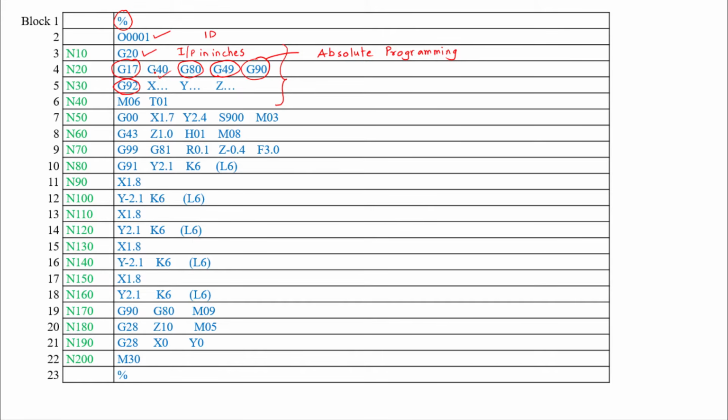So when the part is fixed on the machine table, we need to communicate to the machine tool its location in the work volume. So for that purpose, G92 with XYZ offset values are to be communicated to the machine tool. We will be seeing this in the coming slides. M06 is the tool change, which tells which tool has to be utilized by changing the existing tool in the spindle. So M06 T01 means the existing tool in the spindle will be replaced with T01.